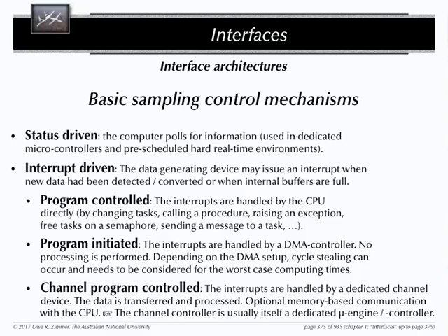Of course, if you waste several gigahertz CPU staring at a pin someplace, that sounds a bit unreasonable. But if you dedicate a small Cortex M3, which takes about 50 milliwatt if it goes full blast, to staring at a line, that may not be the worst idea on the planet. And then you can use the other CPUs to do more interesting things.